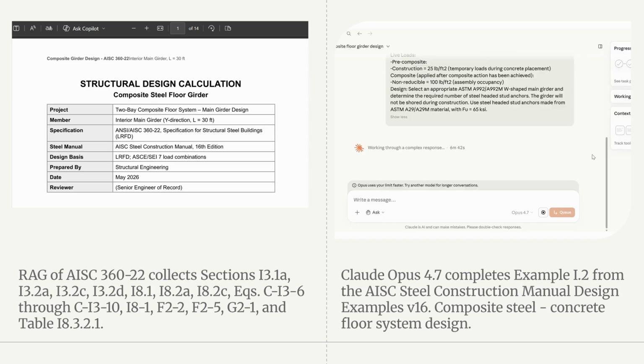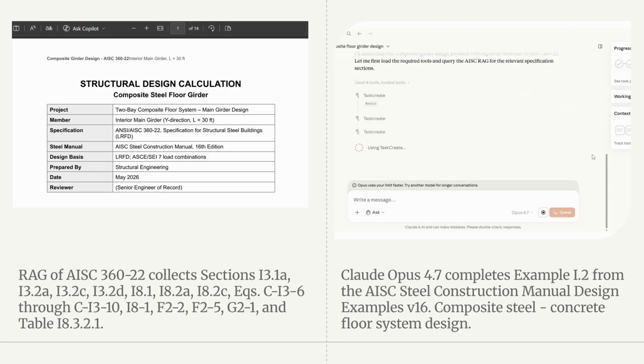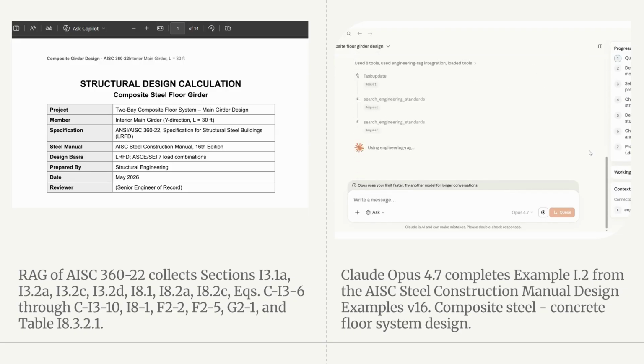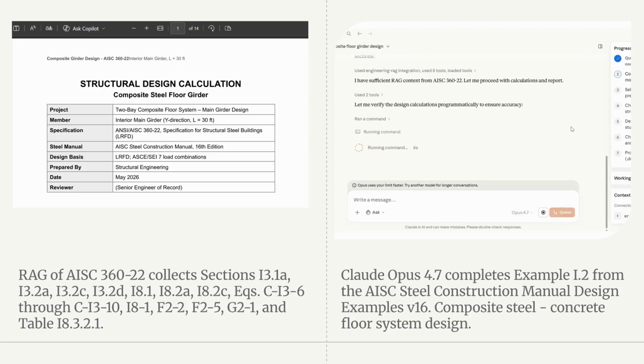The capacities and deflections during construction and during the composite stage are nearly exactly the same. However, Claude slightly overpredicted the construction capacity due to a small calculation error, 708 kips compared with 677 kips. So I flick through this quickly, but of course you can pause it whenever you wish to see more details.